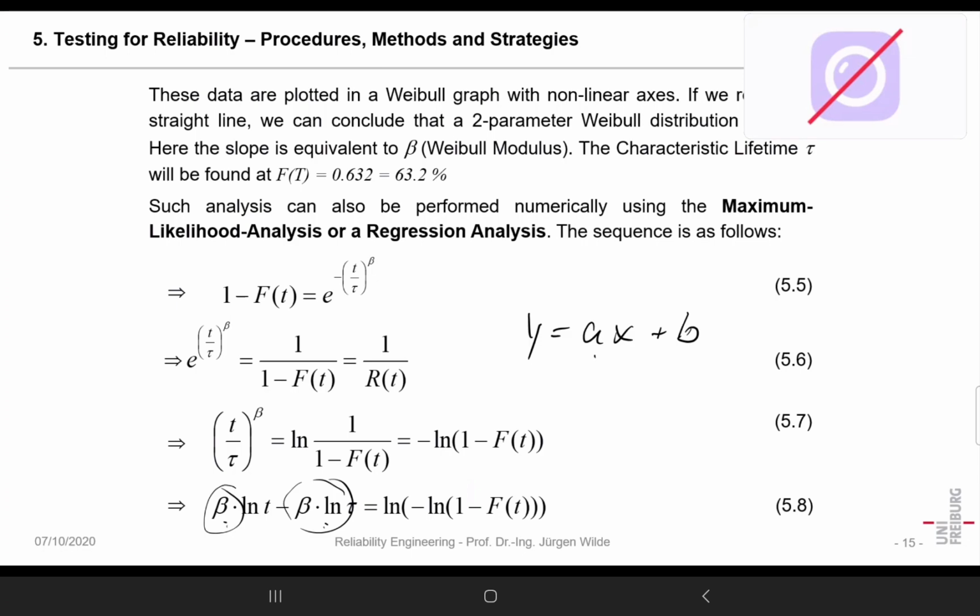On the other hand, sometimes you cannot really distinguish. For instance, if the beta is roughly 3 or so, you can also make a test similarly for Gauss distribution, and you will find out, you will not really know if it's a Weibull or a Gauss distribution, when the beta is around 3 or so. So in the end, what is a quantitative test to find out if it's a certain distribution function?